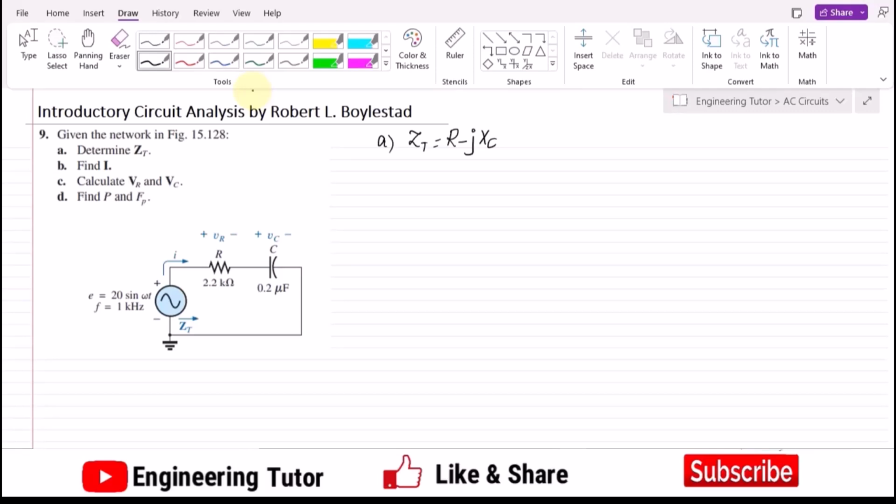Putting the values here, we will get the total impedance, but there is an issue: we are not given the value of X_C, but we are given the value of capacitance, which is 0.2 microfarad. To find X_C, we use X_C equal to 1 over omega C. C is already known, but omega is unknown.